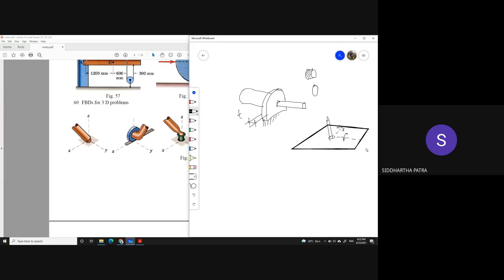So the point actually is, in a physical situation, there is of course some clearance. Okay. In an actual support like this, there is obviously some clearance. Okay, number 1, and number 2 is, when you do consider clearance, then this T doesn't actually have to tend to 0. If it is sufficiently small, that would be good enough.